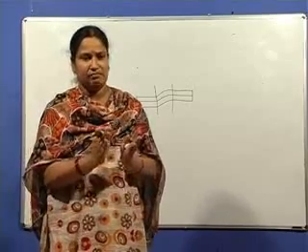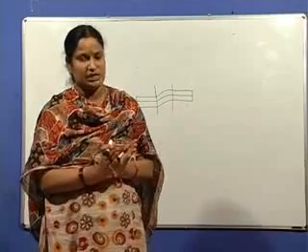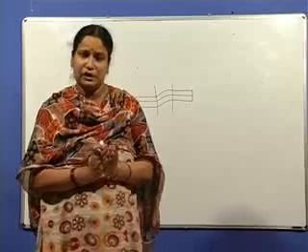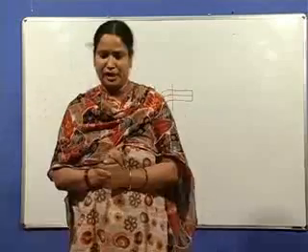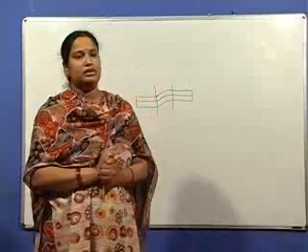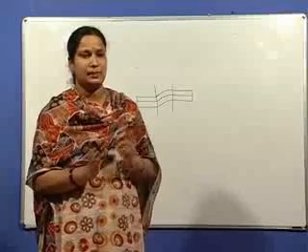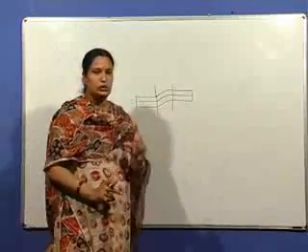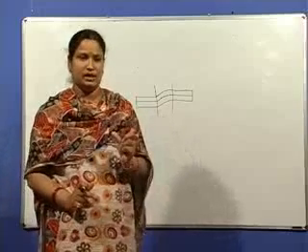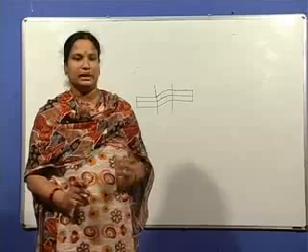That means the metal slightly shears by the formation of dislocation arrays that produce buckling, slight bending along the slip plane direction, which shears the metal several degrees away from its previous position. And moreover, the atom positions do not form a mirror image, unlike in twinning. So this is about the kink bands.